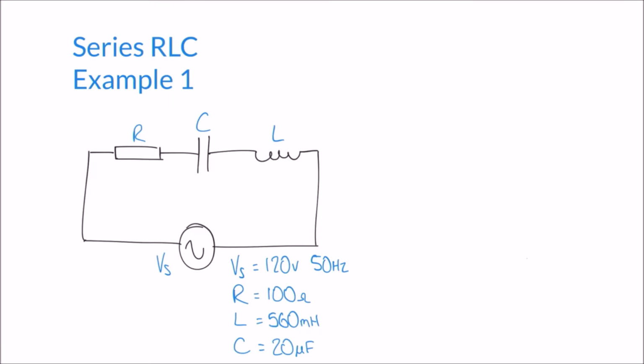The next step in this particular circuit is to calculate the impedance of the whole circuit. And the impedance is really the combination of both resistance and reactance in the circuit. Now the temptation is to say, well, because resistance is measured in ohms and the reactances that we've both calculated are both measured in ohms, the impedance is simply just a case of adding all three of these parameters together. Now, unfortunately, it's not quite as simple as that, and I'll try and illustrate with a sketch.